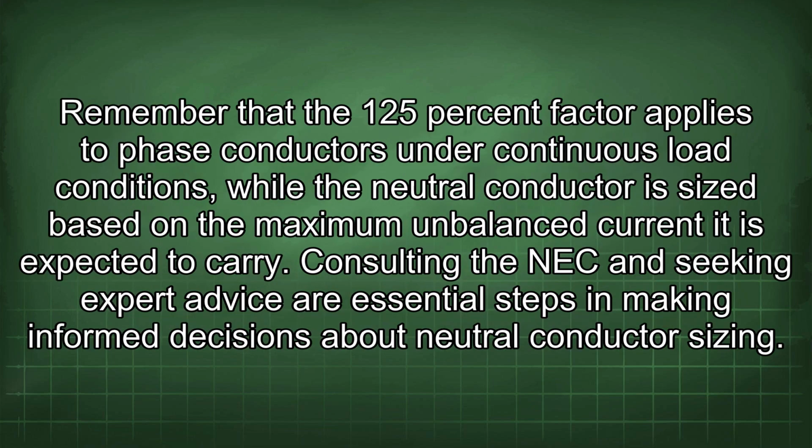Remember that the 125% factor applies to phase conductors under continuous load conditions, while the neutral conductor is sized based on the maximum unbalanced current it is expected to carry. Consulting the NEC and seeking expert advice are essential steps in making informed decisions about neutral conductor sizing.